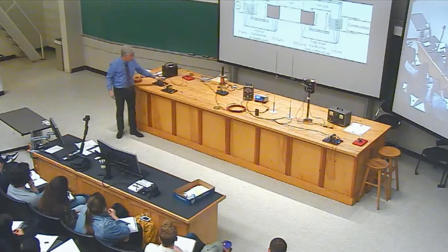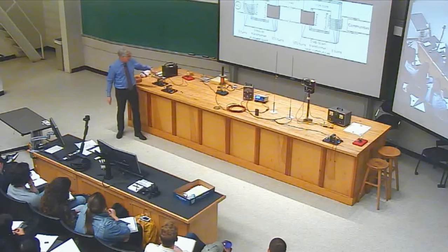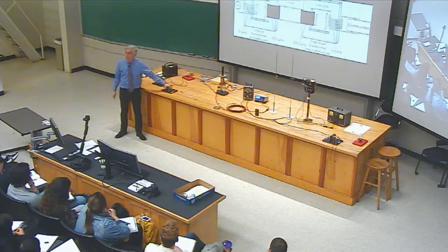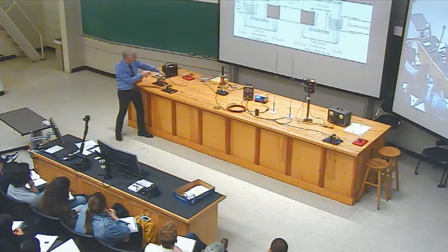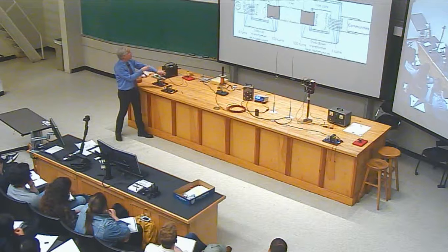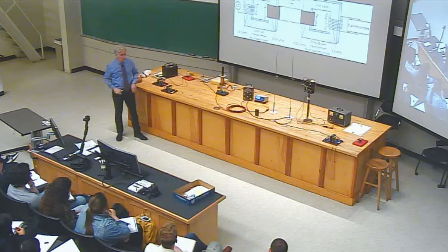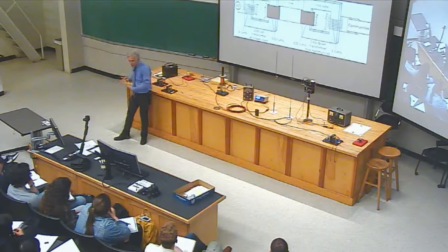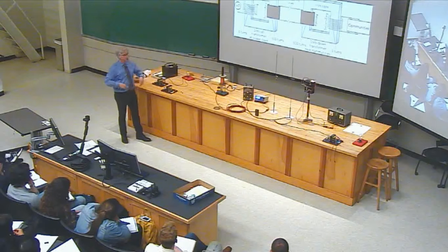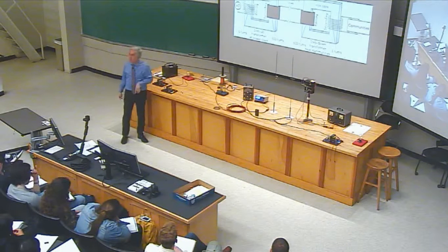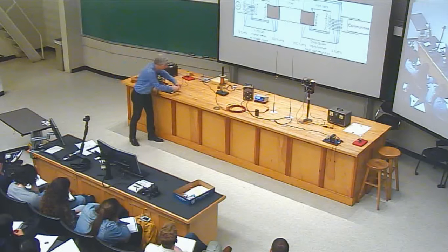I'm taking the 12-volt AC power and putting it into the primary coil of the step-up transformer. It goes in here. These wires are associated with that connection. The secondary coil, which will receive power from the transformer, has many turns in its coil, and therefore it will operate at a much higher voltage rise. And so I will get the high voltage.